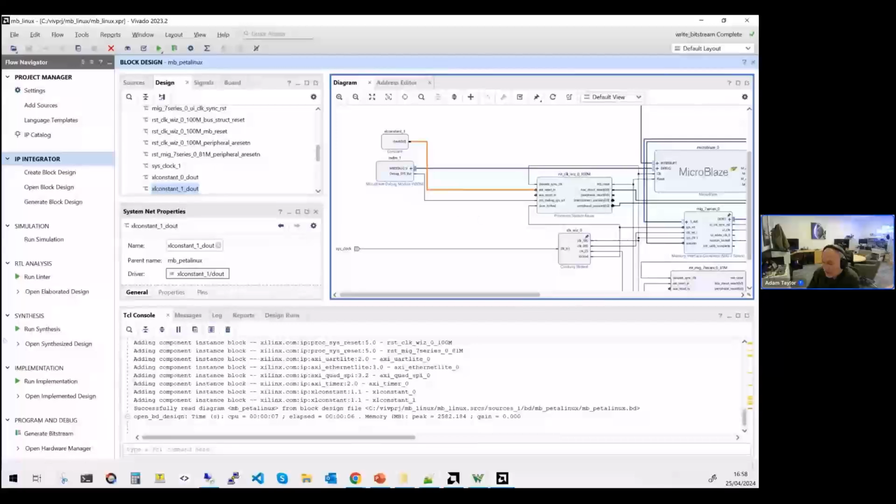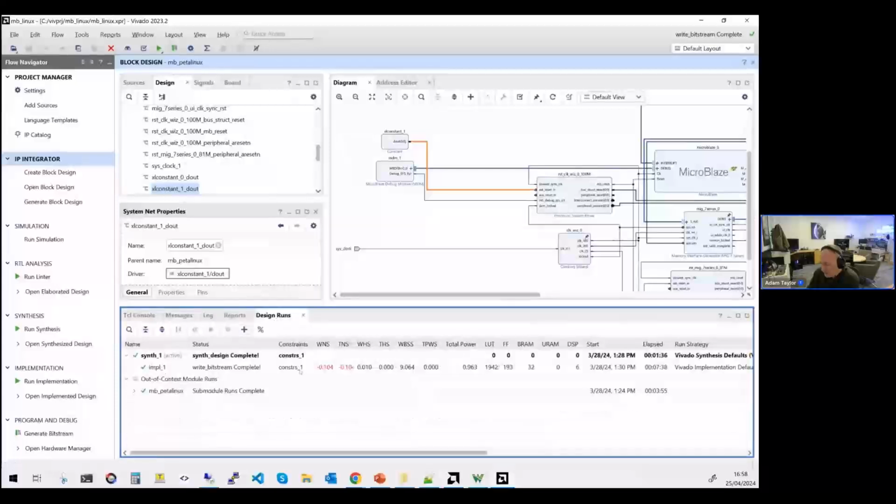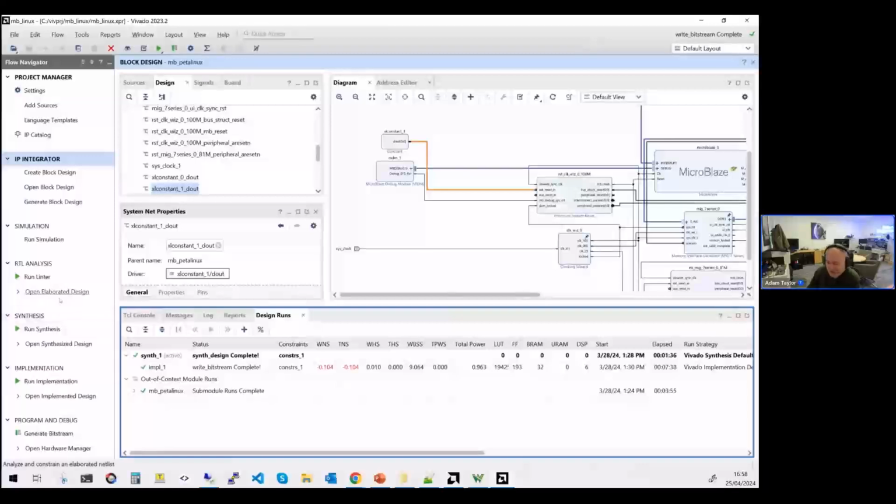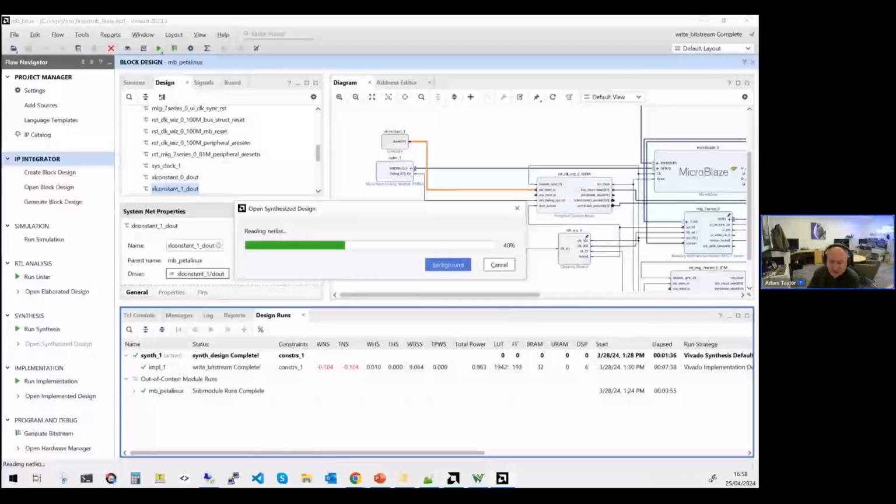What we can do though in here is, this is running on the bench, so I'm not going to worry too much about those timing violations, and I know that, and you wouldn't do that for production. But it should be okay for this. Just don't run it at temperature. It's sat running behind on the bench, and they're only very minor timing violations. So we'll open the netlist, and then I can just show you where the pin is.